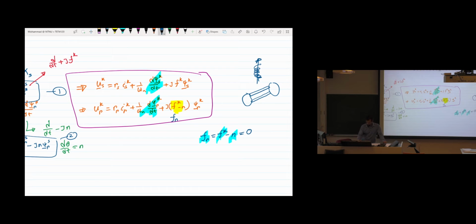We have this flux there, and if the bars rotate at the same speed as fk, you'll see that there is no change of flux in the rotor bar, since they are rotating at the same speed as the stator flux.